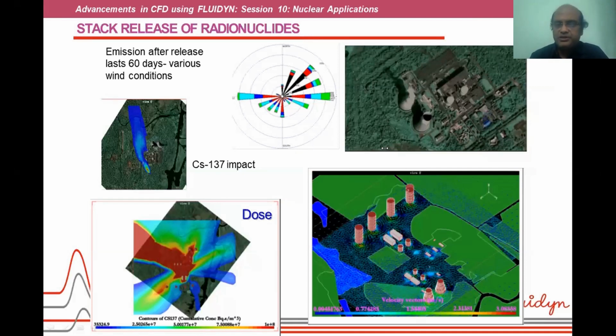Here, the difference is that in Newton's law of viscosity, we assume that viscosity is not a function of strain rate, that is, velocity gradient. Whereas in the case of non-Newtonian fluids, the viscosity depends on the local velocity gradient. So near the wall there will be low viscosity, and at the center the viscosity will be higher. That is why such fluids are called non-Newtonian.